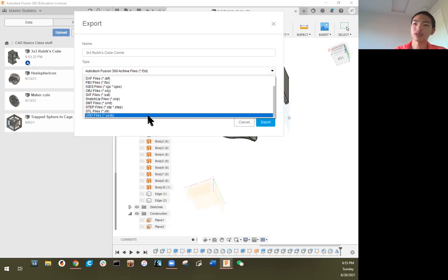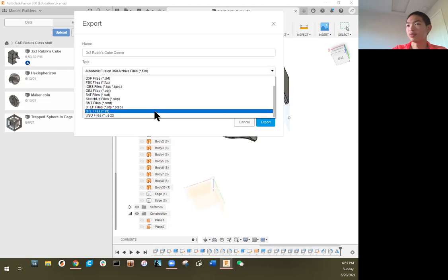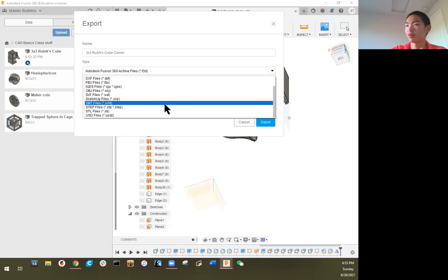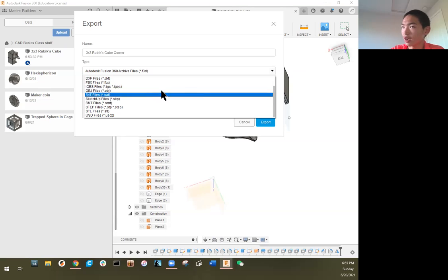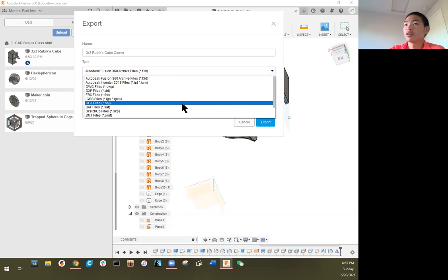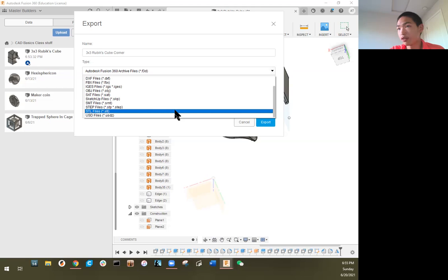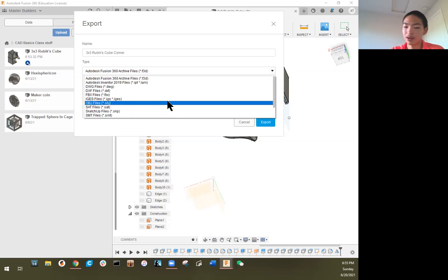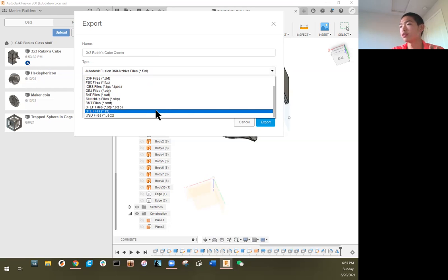And so for exporting these kind of files, you will need internet for Autodesk Fusion 360, but making the actual thing, depending on the tools you use, you probably won't need actual internet to work on it. And so the next thing, for 3D printing, you have two main files you use. You use either the STL file or the object file. Like Jerry said, object and STL are best for 3D printing, and they're what you use.